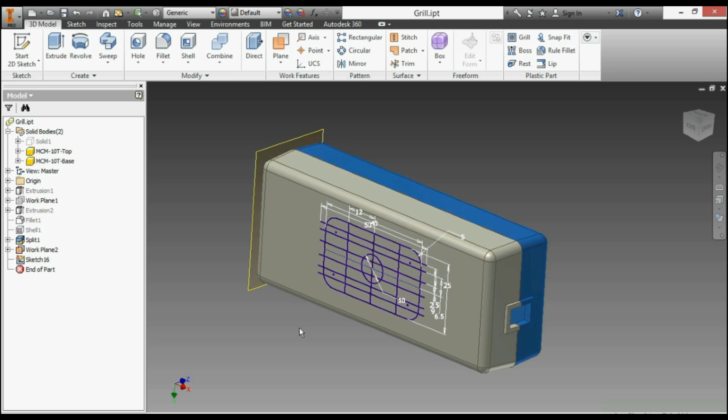If you had them come up short though, for instance, if they were just inside the boundary here, they do not extend like a traditional rib command would. So either have them connect to your boundary or go beyond them. And then I have spar lines, which are 1, 2, and 3, that will act as a supporting structure for my rib network. Now this grill command doesn't have to take place on a flat surface. It actually will wrap itself to curvature as well. I'm just utilizing the flat face of this box for simplicity.